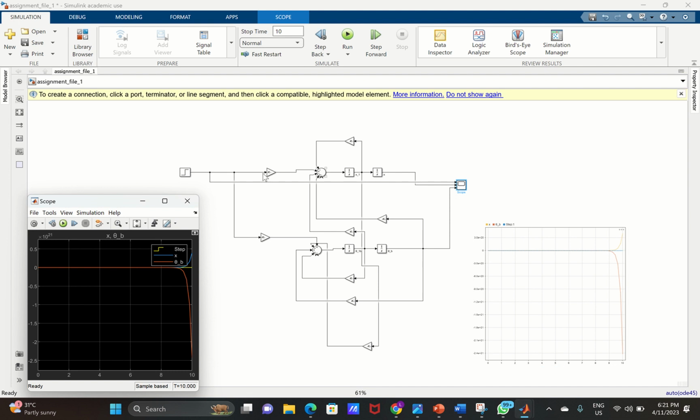system block diagram. For example, here you can see we only have the input, the output, and the system. We do not have a controller anywhere. Maybe to further highlight more, a stable system is one that produces a bounded output for a given bounded input. And as you can see for this, we have a step input, which is meant to be our bounded input, though we are not getting a bounded output, hence the system is unstable. And also, an unstable system is a system that's out of control.